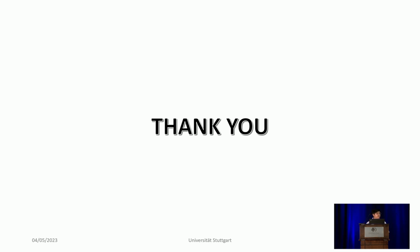Yes, any questions? Kaveh Shamsi, UT Dallas. Thank you for your great presentation. My question is that in the threat model, you assume that the keys are fed by flip-flops that can be flipped using faults? Yeah. So if there are some logic locking circuit-level implementations that don't use those, for instance, you take an anti-fuse and burn it and then just tie the key bit to high, that would sort of thwart something like this, right?